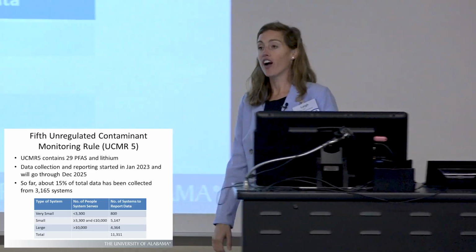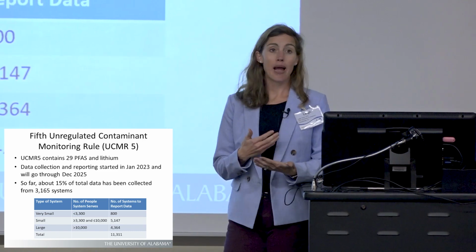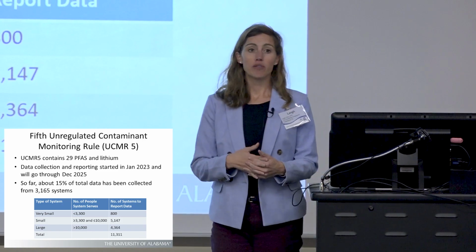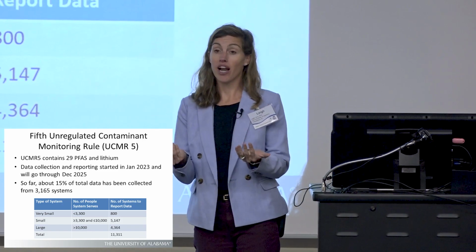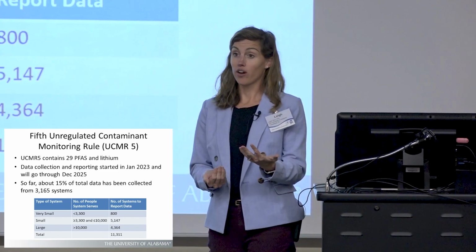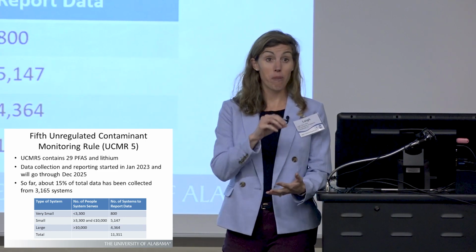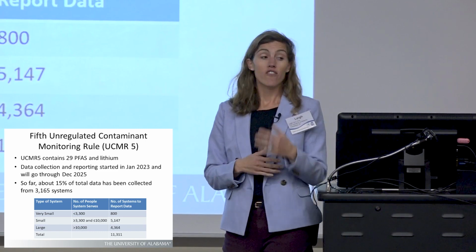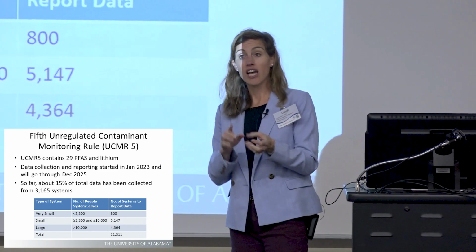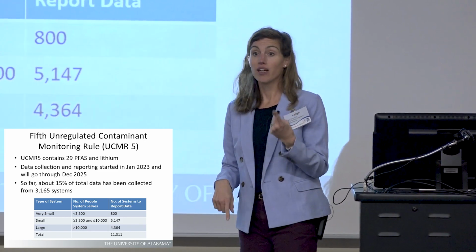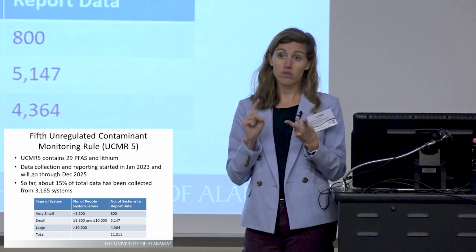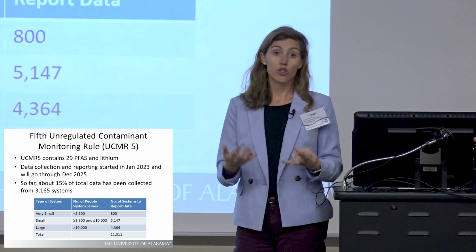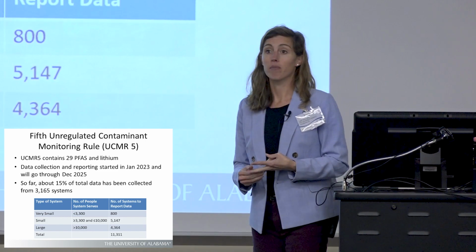So now the EPA also has the Unregulated Contaminant Monitoring Rule. This rule, UCMR 5, is the one that we're currently in. It basically says that if there is a contaminant out there that is maybe showing up in drinking water that we should regulate, let's sample utilities to see if it's present at a concentration that we should regulate. For a contaminant to come into regulation, it has to meet 3 things. It has to be harmful to humans because we're drinking it. It has to show up in the water, and it has to present a meaningful opportunity to monitor and to regulate. So those 3 things.